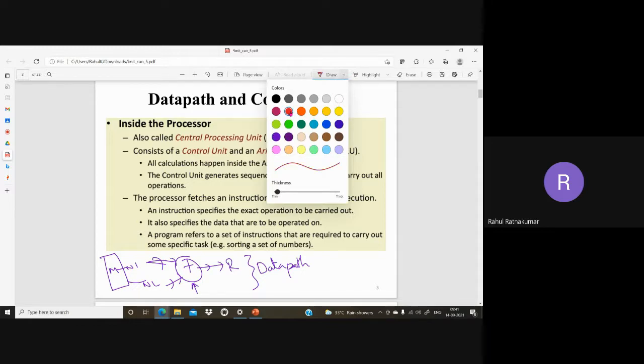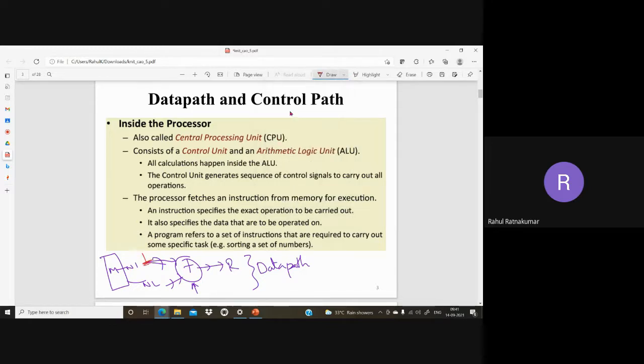For example, we are switching when n1 has come to the register from the memory. There is switch 1, switch 2, and which instruction has to be executed. Maybe adder, subtractor, division, ANDing, ORing. So this has to be told to the ALU, and at what time the output has to be stored. There's another switching here, S3, and it is written back to the memory. So it is a read operation or write operation in the memory. Either we are loading or storing, right?